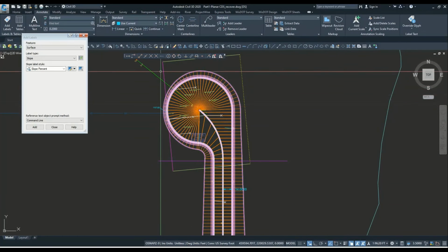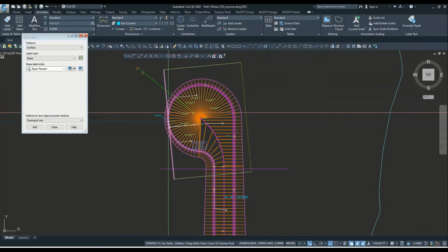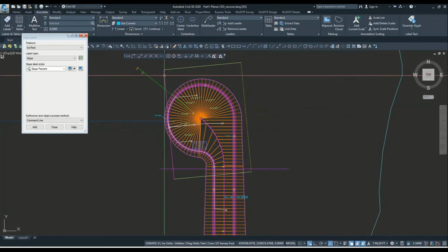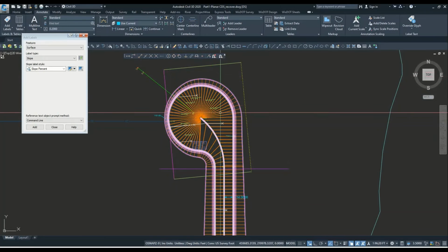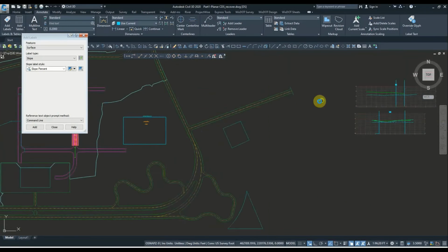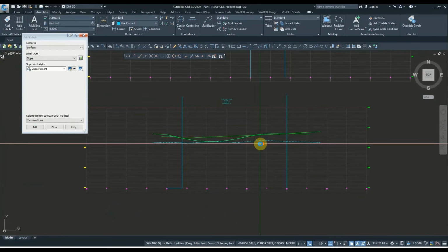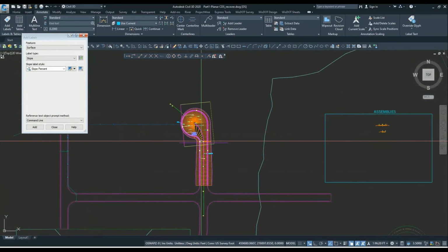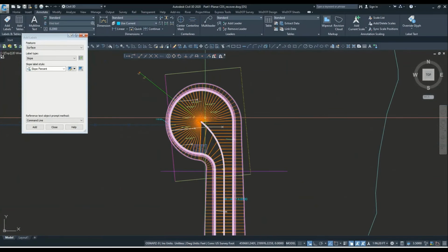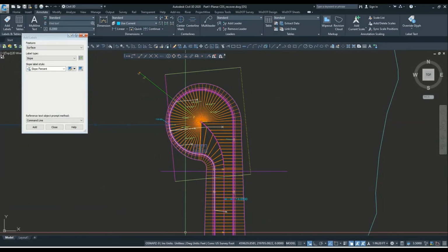And so what this allowed us to do is that we selected a low point, graded out at 2%, and on the profiles we matched up to the throat of the cul-de-sac, and then in the end we were able to come out with a planar cul-de-sac where we ensure that all the drainage is going to the correct location.